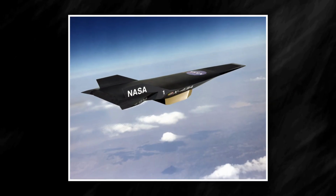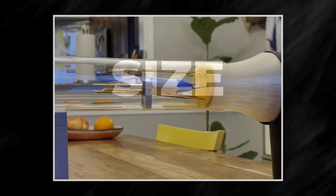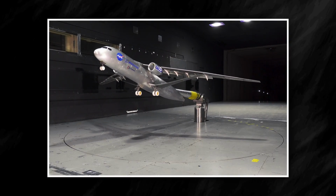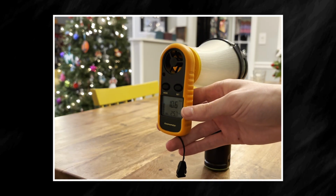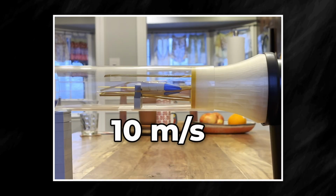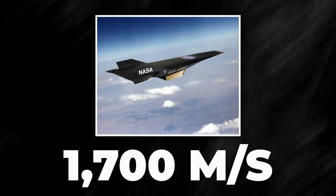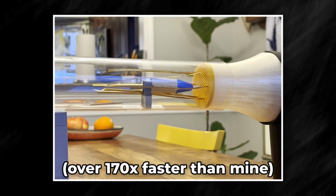If I was working on a hypersonic vehicle, my model wind tunnel wouldn't be suitable to test it. This is mainly due to the size and speed of my model. Because my wind tunnel is so small, I wouldn't be able to create a very accurate model of my hypersonic vehicle. Larger wind tunnels allow for larger models, which makes it easier to match real flight conditions. Additionally, my wind tunnel only blows air at about 10 meters per second. Because of this, I can only test vehicles traveling at that speed. Hypersonic speeds start at Mach 5, which is roughly 1700 meters per second. If I wanted to test a hypersonic vehicle, I would need a wind tunnel that can reach much higher speeds.